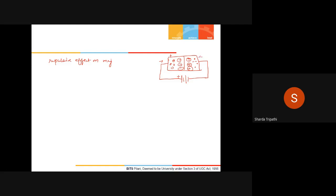So here there will be a repulsive effect which is going to push the majority charge carriers towards the junction. And when the value of V is large enough, the tendency of diffusion will overpower the tendency of drift and the majority carriers will start flowing across the junction, thereby leading to the flow of what we call as forward current.